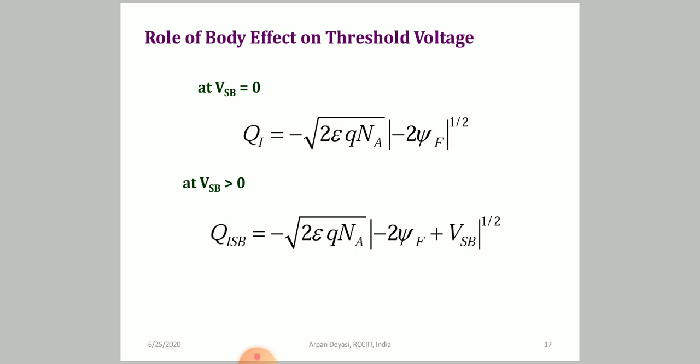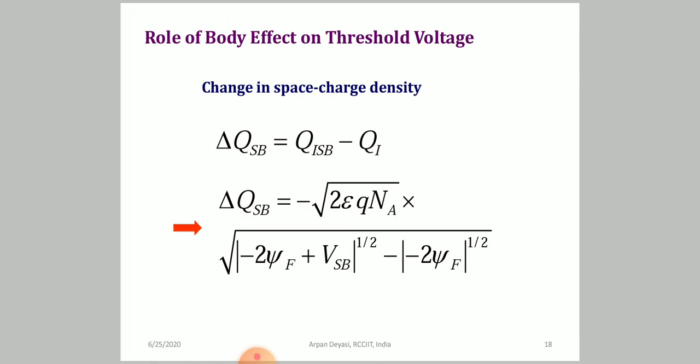And now this is the QI, the first expression. We have considered that the MOSFET is a 3-terminal device. It's perfect. But if the body effect comes, then obviously the Fermi potential will be modified, and it will be added with a function called the source to body potential. Now, the source to body potential starts to develop, and what it tries to do is create a hindrance to the carrier flow. So naturally, the inversion charge in the presence of the effect will be added with the Fermi potential, and once you have added, you will get the term.